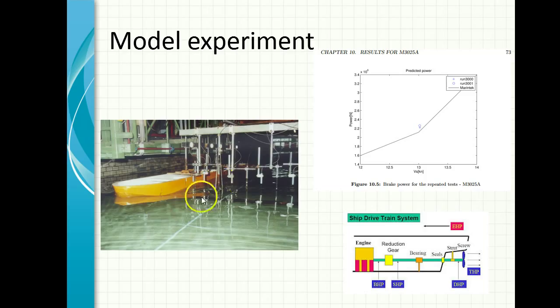And a carriage in a long towing tank. India also has some very good testing and towing tanks in Pune and in Chennai, at IIT Chennai, and there these kinds of calculations can be done. Theoretical calculations without resorting to a model test can also be done, but a model test will give a much better approximation of the powering requirement.